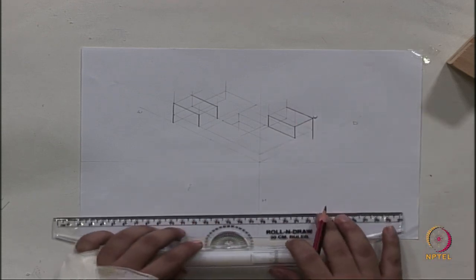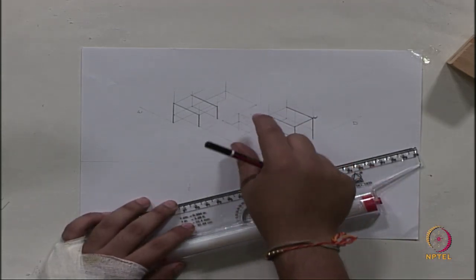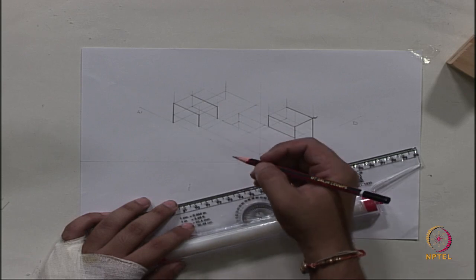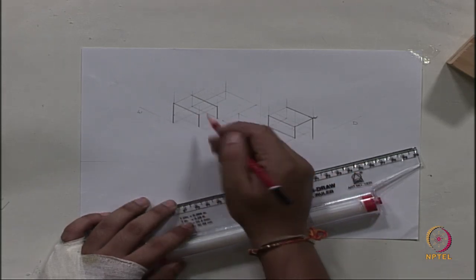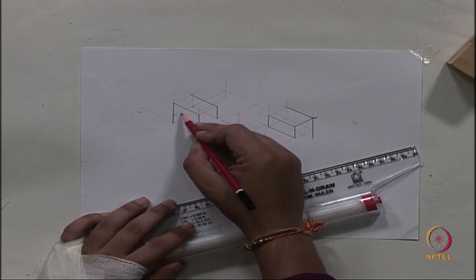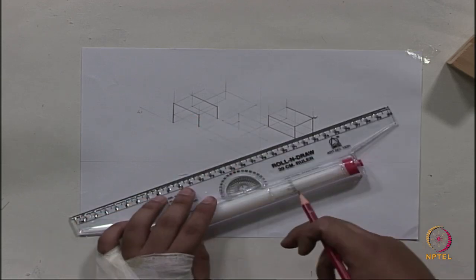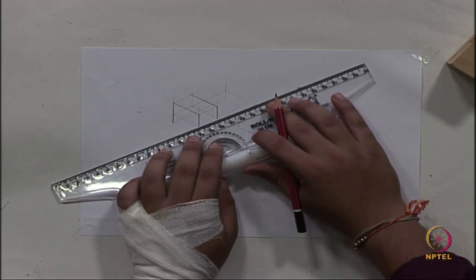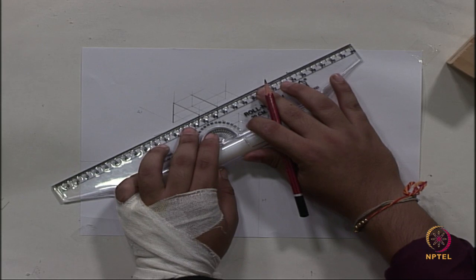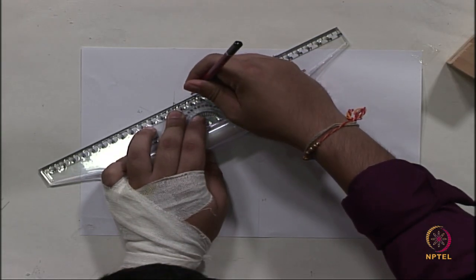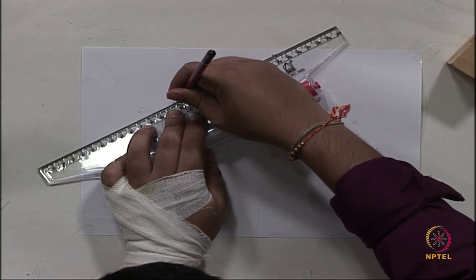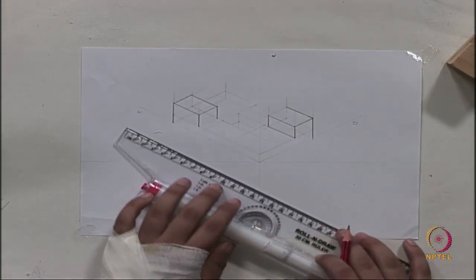If I were to start drawing the cuboidal base or the rectangular base using outline or dark lines, there would be some trouble, since this part of the rectangular slab will not be visible. So, I would need to erase that part if I started my drawing using outlines. So, start drawing using construction lines only, and based on the visibility, convert these construction lines into outlines.